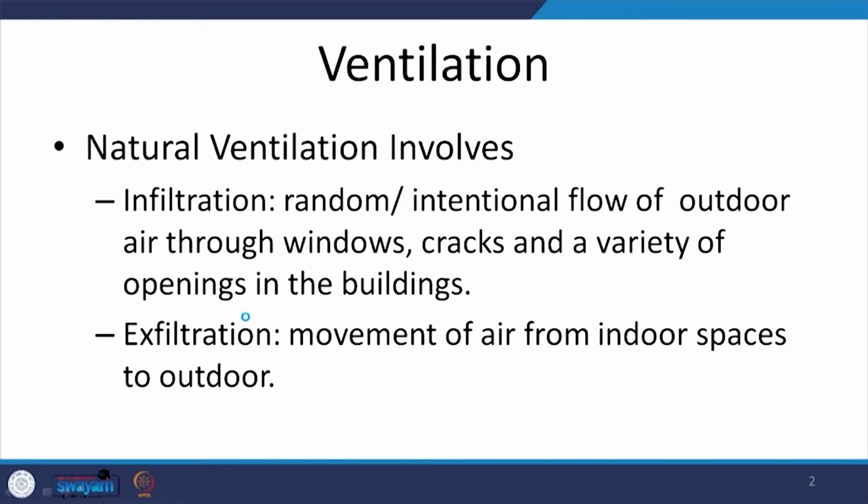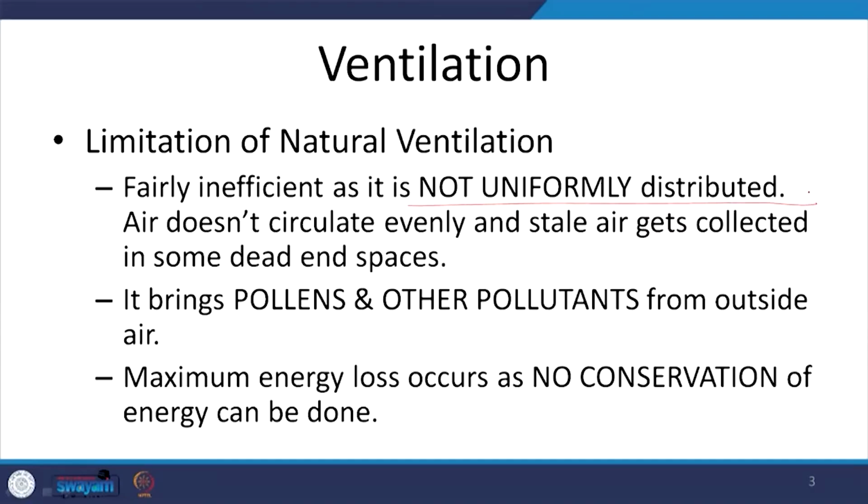When we are looking at providing adequate natural ventilation, we have to know its limitations. First of all, it is often not uniformly distributed through the building, because by virtue of the design, which may create eddies or may not create a wind current, the air movement in certain pockets of the building is poor. Wherever the air does not circulate evenly, stale air gets collected and dead end spaces are created because of natural ventilation.